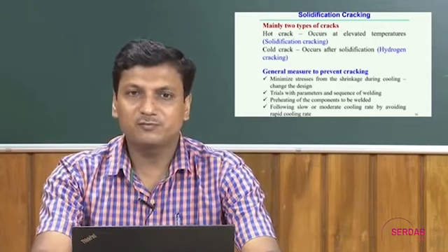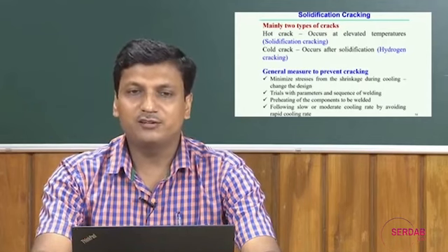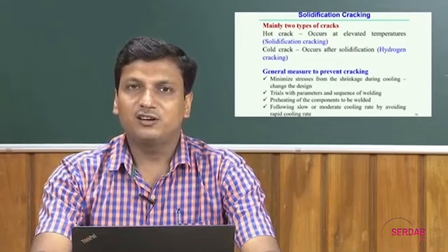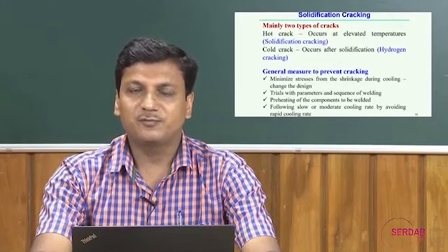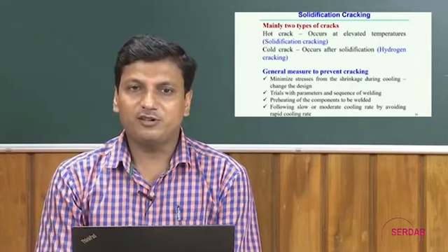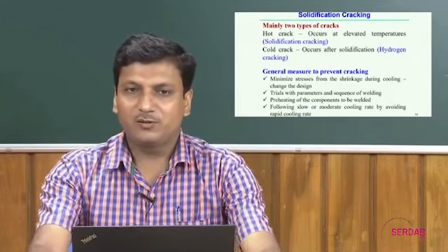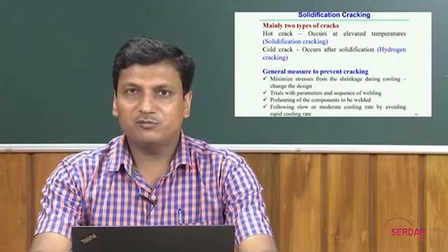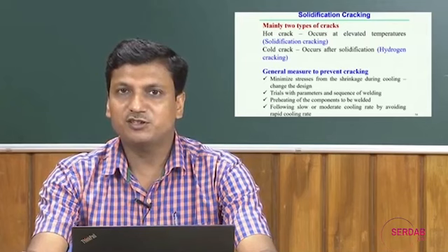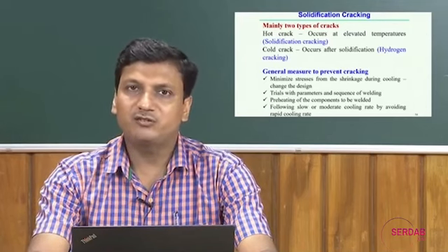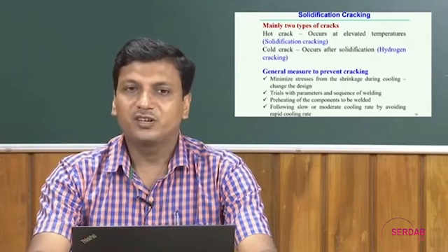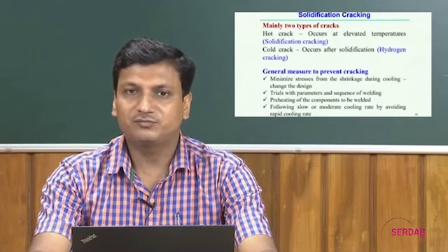the cooling period, and to do that it depends on a change in the design. It is not always possible to completely avoid the development of stress during the cooling phases, because maybe a phase transformation happens that induces, in most cases, some amount of residual stresses.